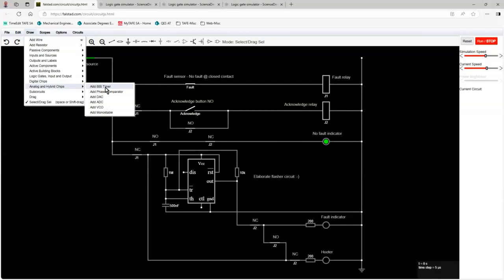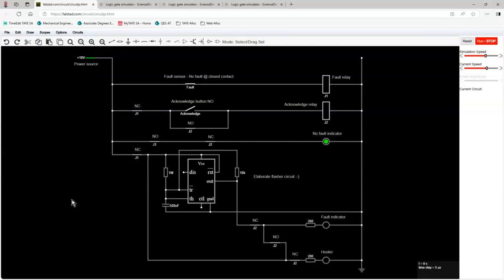It's basically a hardware element, and I did have to put a couple of components around it to make it a flasher. So that element plus this resistor is just feeding back the output to that input there. 1 meg, this is the charging capacitor. The capacitor gives you the timing, so it's an oscillating circuit.